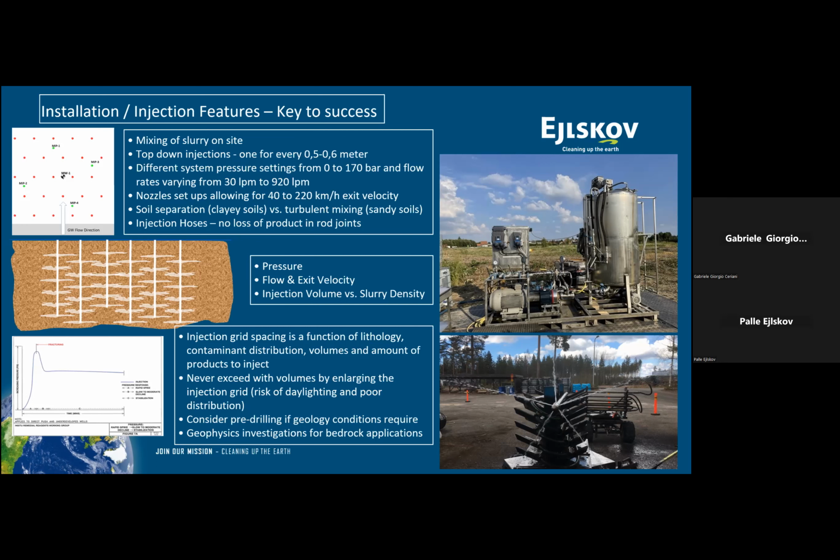Over the years, we have been listening to feedback from people thinking that sand is an easy geology to inject into. It's actually probably the most complicated. Clay becomes almost easier to inject when you have the right equipment.